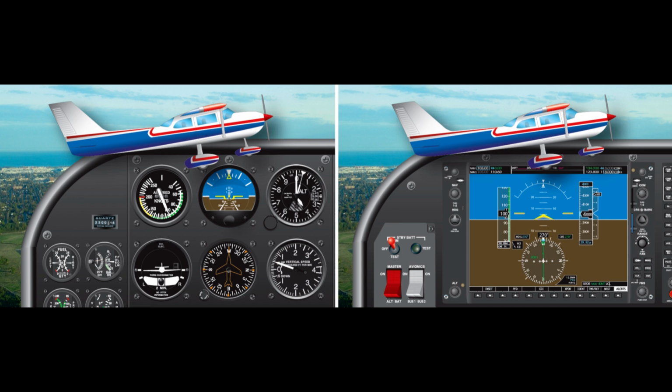5. Fixation on the airplane's nose during straight climbs, resulting in climbing with one wing low. 6. Initiating a climbing turn without coordinated use of flight controls, resulting in no turn and a climb with one wing low. 7. Improper coordination resulting in a slip that counteracts the rate of climb, resulting in little or no altitude gain. 8. Inability to keep pitch and bank attitude constant during climbing turns. 9. Attempting to exceed the airplane's climb capability. 10. Using excessive forward elevator pressure during level off, resulting in a loss of altitude or excessive low g-force.